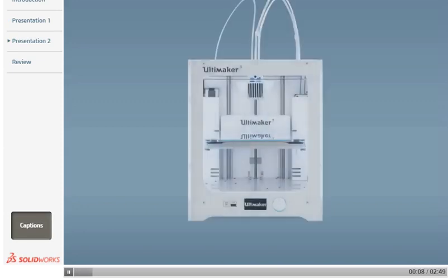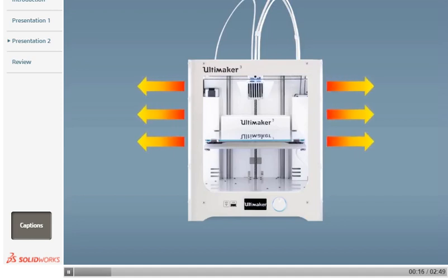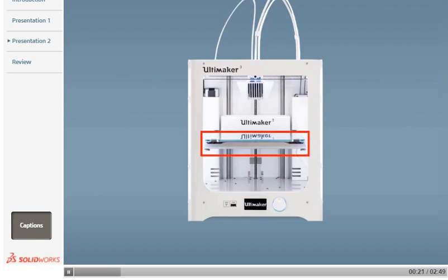Because the different printing methods vary quite a bit, the 3D printing machines also vary in size and structure. An FDM printer, such as this Ultimaker 3 model, has an open build area that's accessible during the printing process. This helps the heat dissipate during the print by increasing airflow. It also gives the build plate a much larger distance to move downward, which means you can print taller parts.